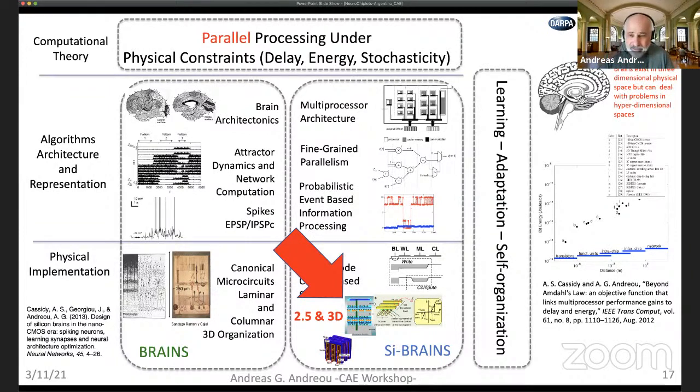Even though this is not shown here, there's a big gap, about 2 orders of magnitude, going from intra-chip to another chip to the board and going back to the chip. That gap indicates that going 3D or 2.5D would be beneficial, because we don't need to move the bits in a two-dimensional space, but we can move laterally up and create a 3D stack.